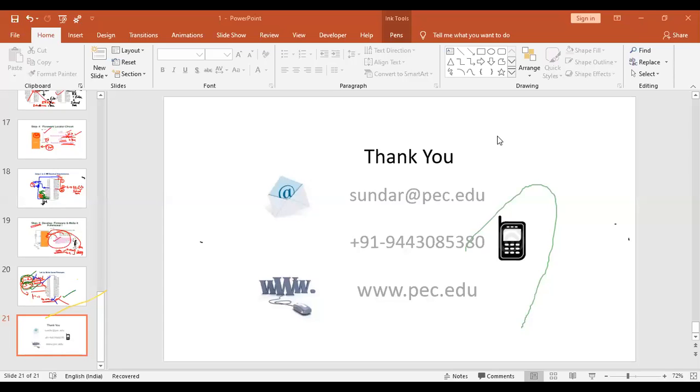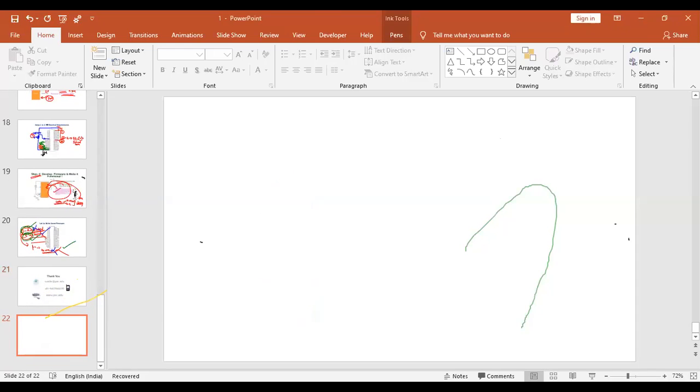Resistor 8.2K, why? Resistor 8.2K is not decided by us. It is given in the manufacturer's data sheet. The resistor and the capacitor's time constant should be good enough to complete the reset operation. One of you has asked a question, I think it is Sivasankar. Sivasankar has asked, why are you putting 8.2K in the reset circuit? Okay, so let me give you a brief idea about it. The reason why we are giving 8.2K is this.